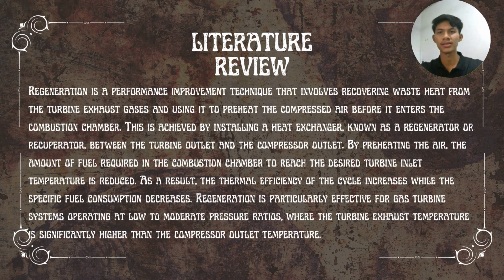Next is regeneration. What is regeneration? Regeneration is a performance improvement technique that involves recovering waste heat from the turbine exhaust gas, and using it to preheat the compressed air before it enters the combustion chamber.